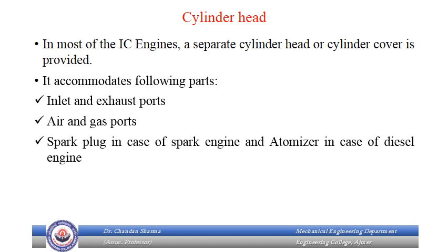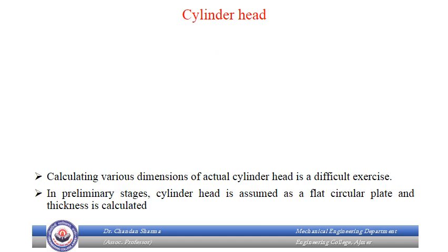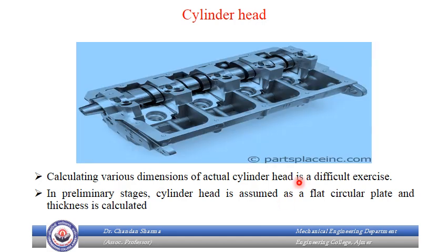A separate cylinder head is required because it accommodates the following parts: inlet and exhaust ports, air and gas ports, spark plug in case of spark engine, and atomizer in case of diesel engine. This is a picture of a common cylinder head used for a four-cylinder engine.